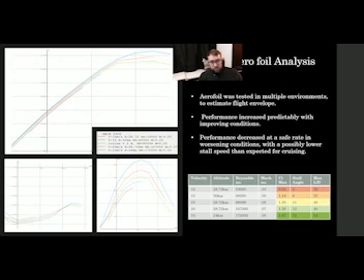But at 30 km altitude, the aerofoil produced only 1.14 CL max, stalling at 6 degrees. And at 10 meters per second, the max CL was even lower at 0.094, stalling at 4 degrees. But this may actually mean the aerofoil has a lower stall speed than required or predicted, but more analysis and real experimentation would be required to confirm this.